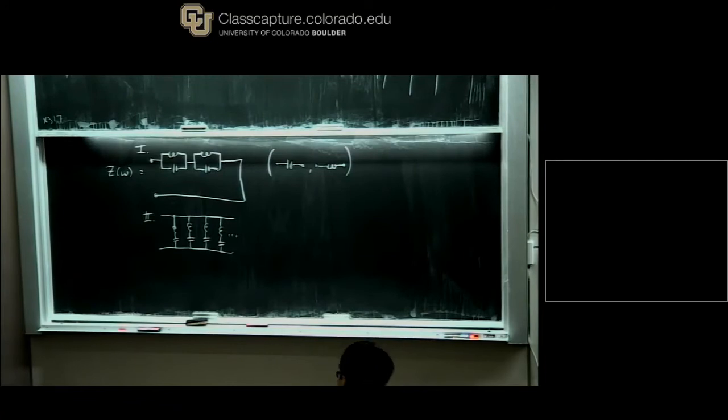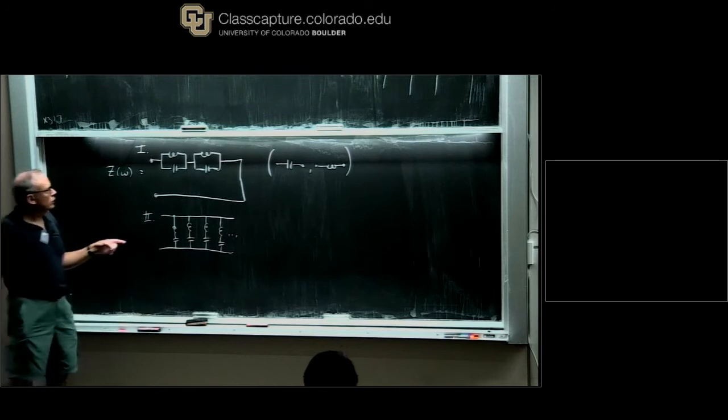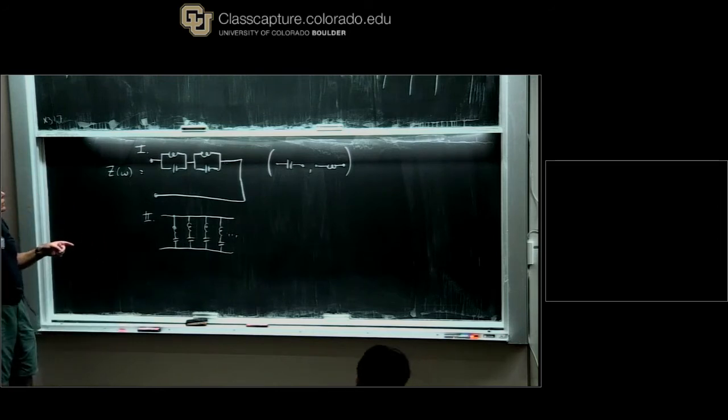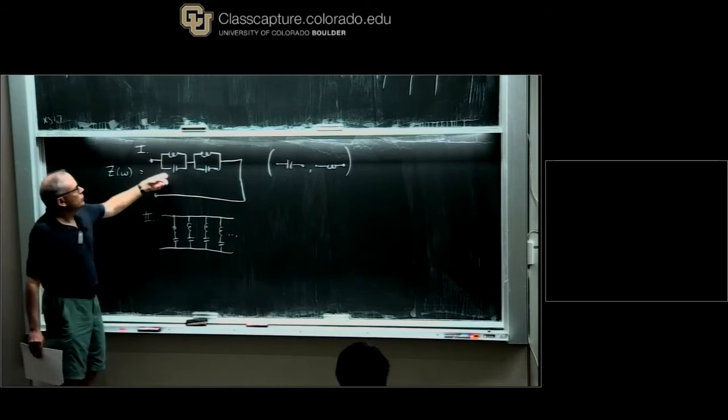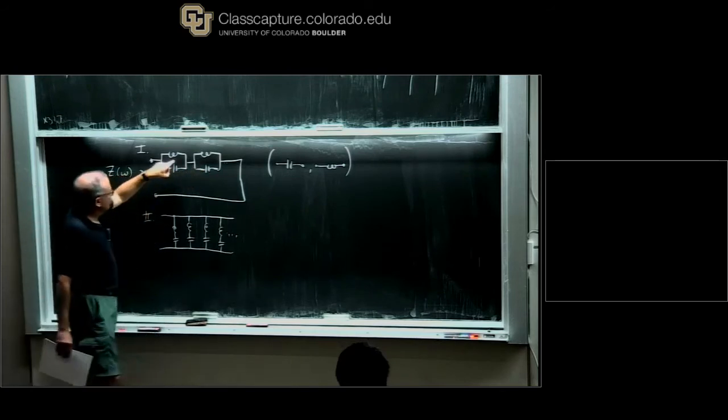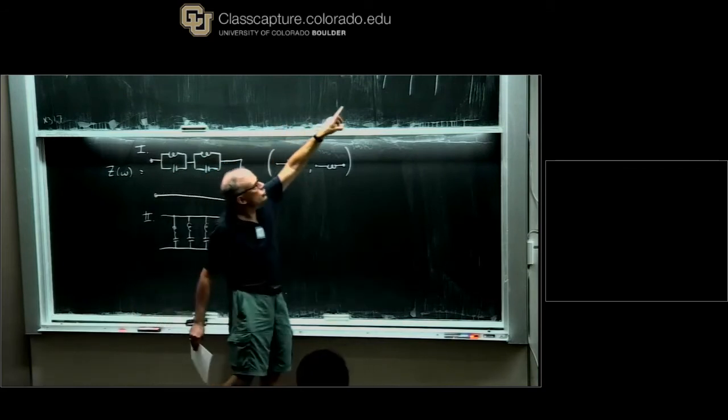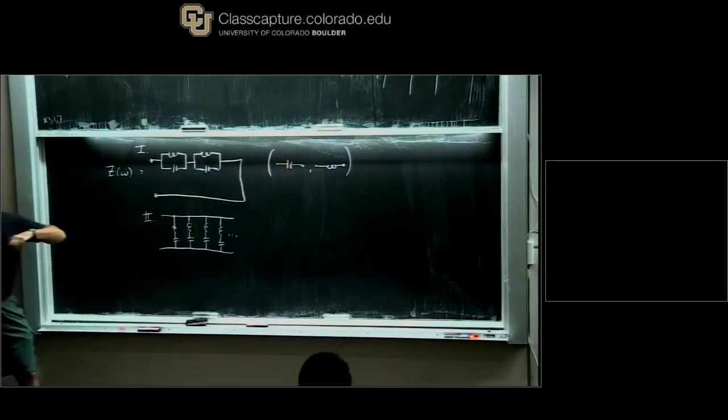So like representing an analytical function by some. Yes, it's indeed an observation that since it has simple poles on the axis, then you have a partial fraction representation of that, and then each term in that expansion is representable exactly as an LC circuit. It's also a kind of diagonalization. This is more associated with the Z because there's a simple relation between each of these sections and the poles of Z, whereas in this case it's a correspondence to the poles of Y, the admittance.